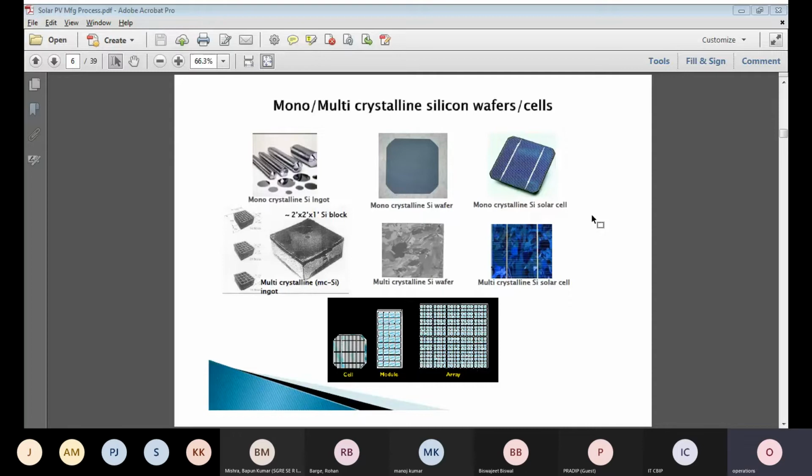If you take watt peak into consideration, monocrystalline will give 400 watt peak in 158 size, around 450 watt peak module in 166, 500 to 550 in 182 mm, and above 600 to 670 in 210 mm modules. As the cell size increases, the module size and the power of the module increase. So indirectly, the BOS project cost will reduce due to this.